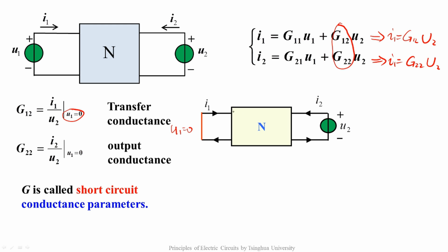For this two-port, if inside the network there is a controlled voltage source in parallel to port 1, there will be a mistake in analysis when port 1 is short. So we can't measure all the two ports G parameters by letting two ports be short. It's also one of the reasons why we need several parameters to describe the two-port.